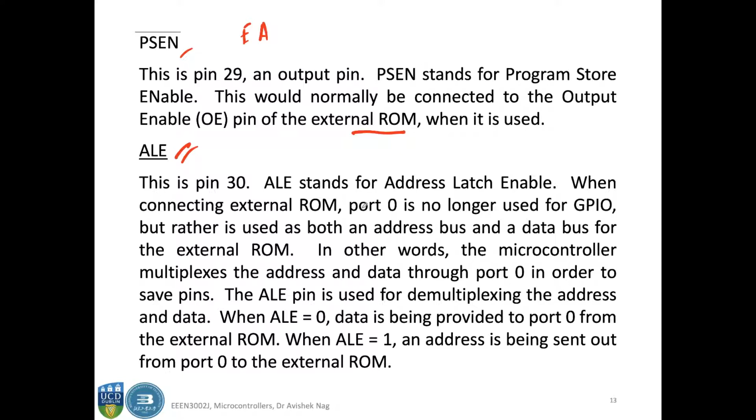Let's continue. So ALE stands for address latch enable, and this is a pin that is used for multiplexing, or rather demultiplexing, actually both multiplexing and demultiplexing, the port 2 of your microcontroller for addressing and data purposes.